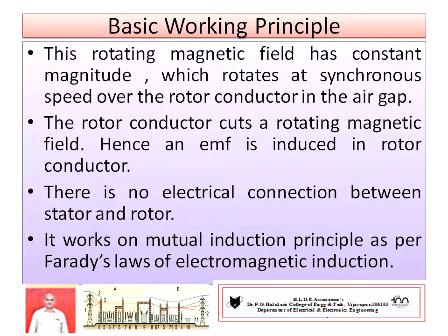This rotating magnetic field has a constant magnitude and rotates at synchronous speed over the rotor conductors in the gap. Hence, this magnetic field splashes over the rotor conductors, and the rotor conductor cuts the rotating magnetic flux.